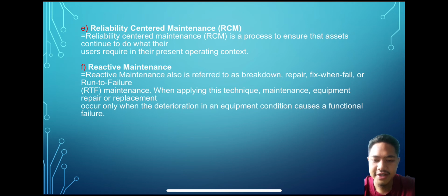F. Reactive maintenance. Reactive maintenance, also referred to as breakdown, repair, fix when failed, or run to failure, RTF maintenance. When applying this technique, maintenance, equipment repair or replacement occur only when the deterioration in an equipment condition causes a functional failure.